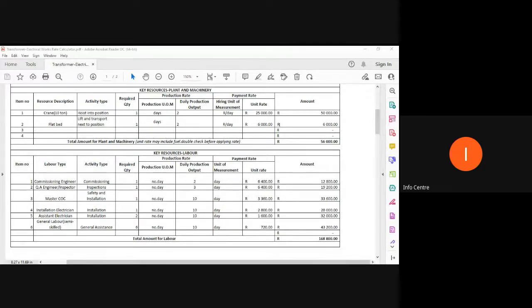Let me give you a practical example. If I'm excavating for trenches, and I'm excavating in a soft area, and I know that I'm not expecting clay, the daily production output of, let's say I'm using plant, a TLB, will be plus minus 50 meters per day on average, right? Now let's take this very thing and then remove a TLB and put humans. You'll realize humans will actually produce lower than the actual plant. So those are the things that you need to take into account as it relates to the different production outputs.